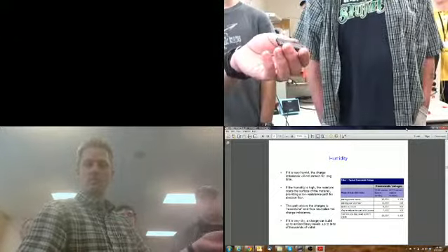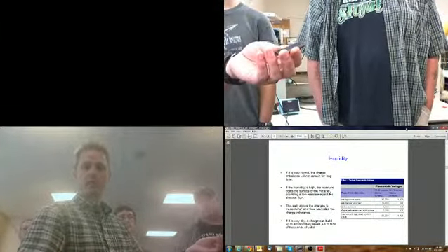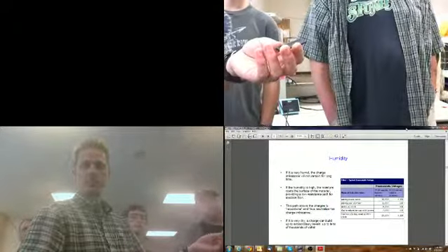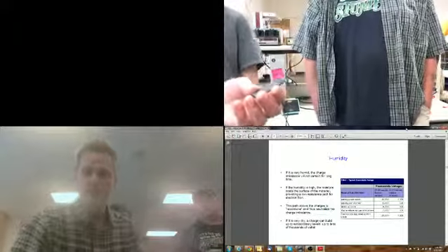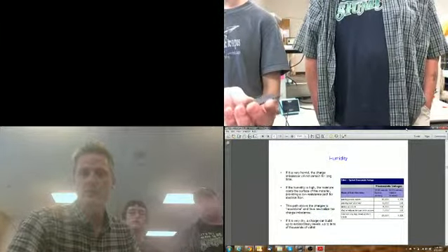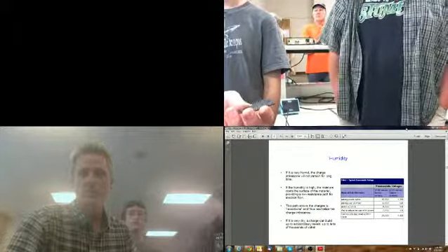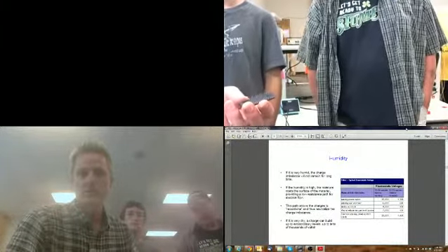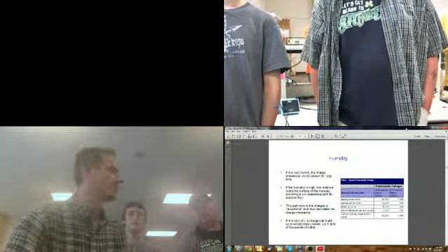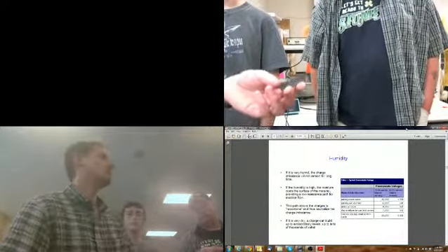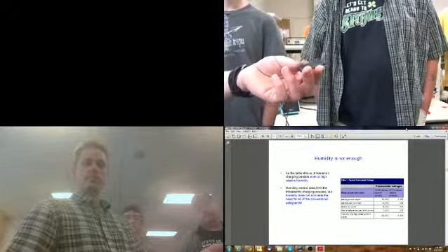It says typical voltages walking across the carpet, 35,000 volts at 10 to 20% relative humidity. Walking over vinyl floor, 12,000. Worker at bench, 6,000. So these are the voltages you can generate. Common poly bag picked up from the bench, 20,000 volts. So it's very significant damage that could occur.